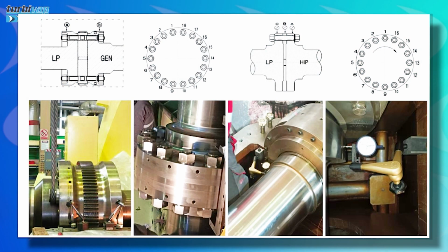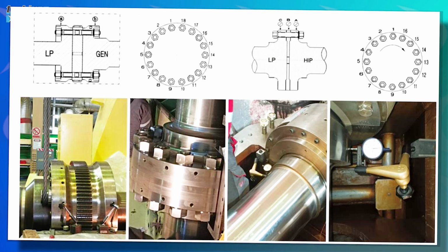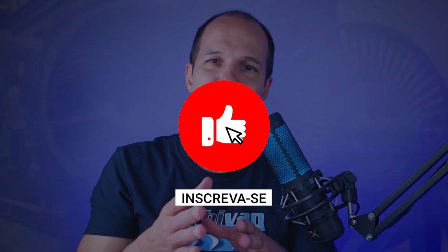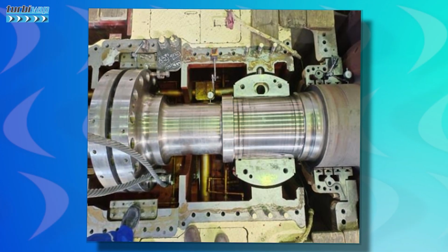So, specifically in the steam turbine, what we do in this type of stop, in this pit stop, the typical scope includes the inspection of the bearings. So we open the covers, usually not the whole casing, okay? We open the bearing covers and we visually inspect the shoes. There, we measure the clearances, look for scratches or signs of overheating in the Babbitt and perform non-destructive tests called NDT, such as penetrant liquid to see cracks or ultrasound to check Babbitt adhesion to the shoe.